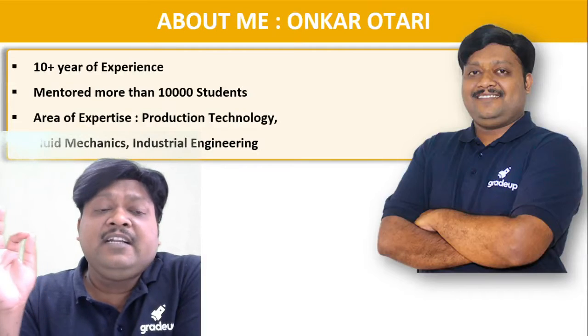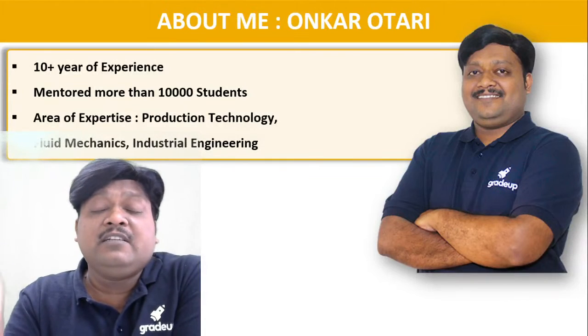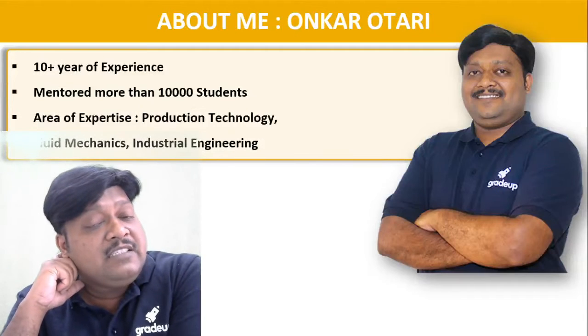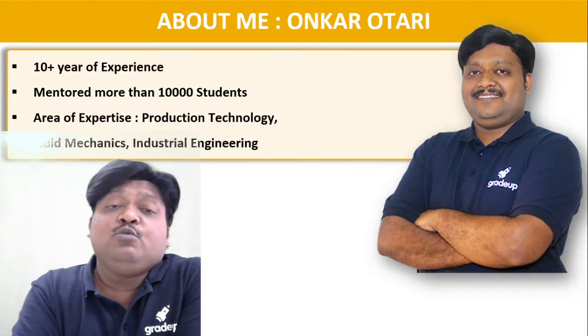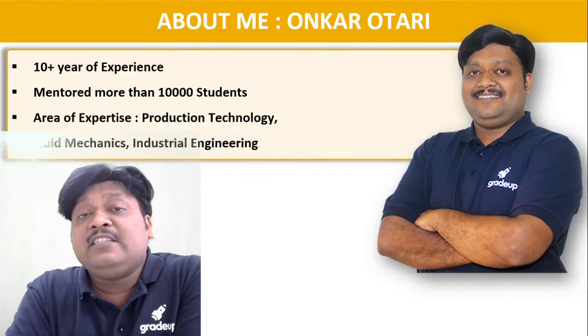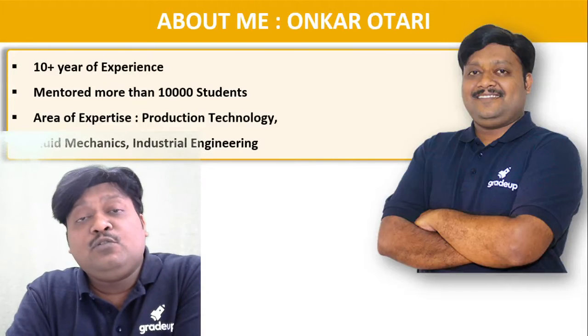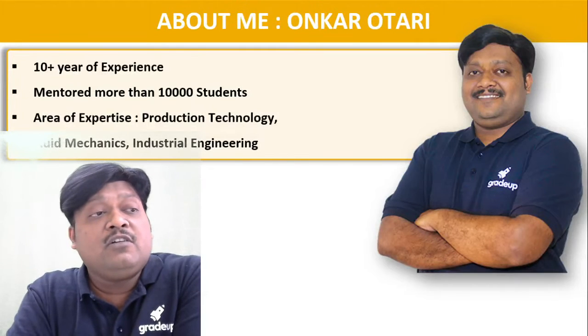Then we also discussed how to calculate the work done in the deformation zone, which is equal to k into epsilon f to the power n divided by n plus 1, which is the work done per unit of volume. And if you want the work done in newton meter or work done in